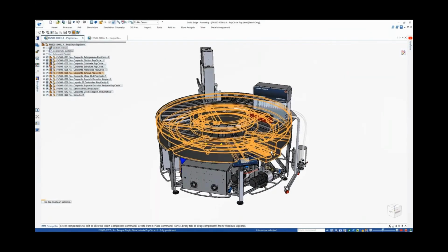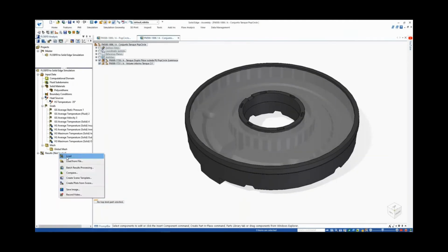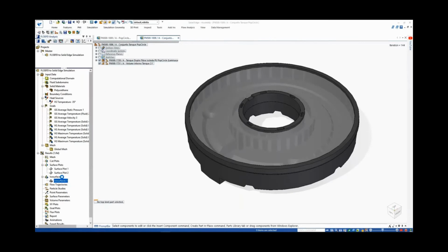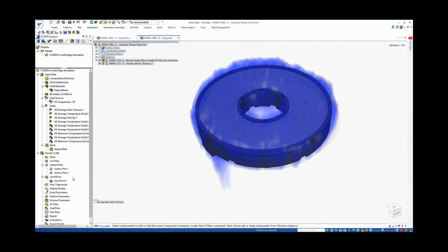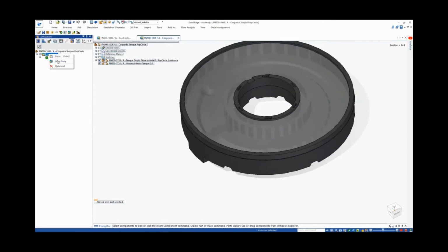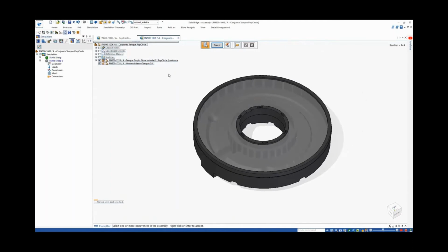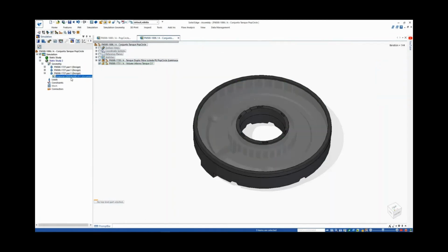In addition, with 2021, we're able to get the fluid dynamics and structural or thermal at the same time. So focusing on the tank containing the liquid bath that freezes the popsicles, looking at the results of this thermal flow study, we can see how the cooling liquid interacts with the assembly. Now let's get the structural analysis set up. So something new for 2021 is the ability to suppress or remove any components directly from the simulation pathfinder. So make it easier for your geometry study.